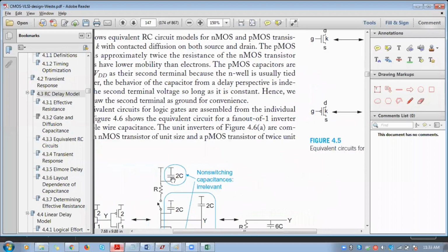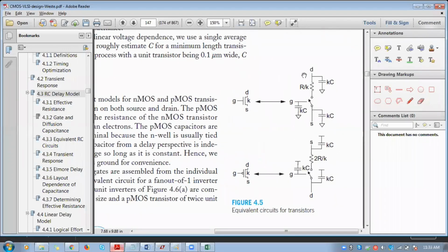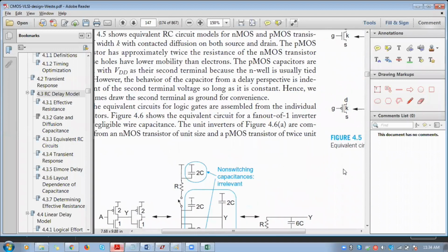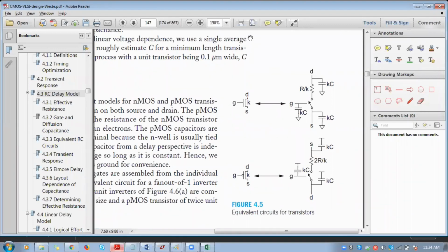The shortcut we have seen for how to calculate the K will always satisfy the equal amount of current flow, so no need to worry about that. Actually, this is the concept behind how to set the K value. Whatever equivalent resistance you are getting, that equivalent resistance has to be equated with the normal R to find the K. Here also, in the case of CMOS also. If you follow that shortcut, we will automatically get the K value for the same output current. Are you all clear, or is any elaboration required?